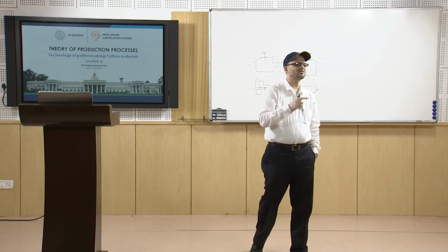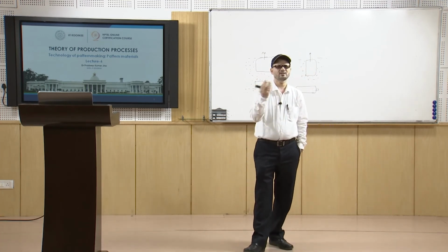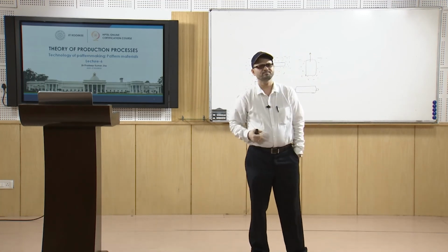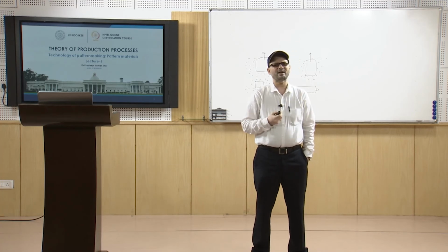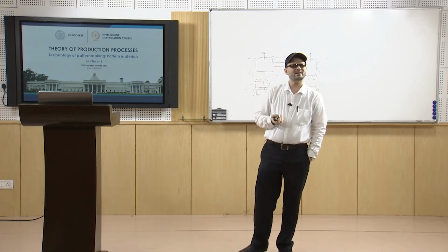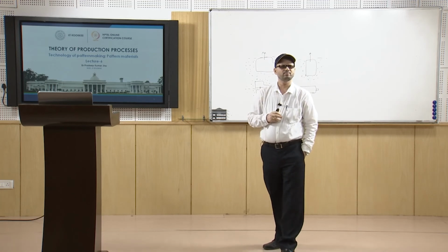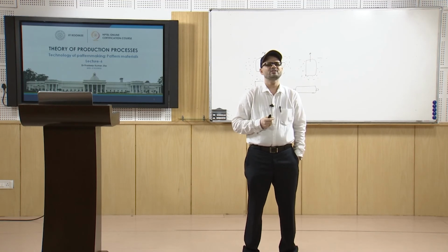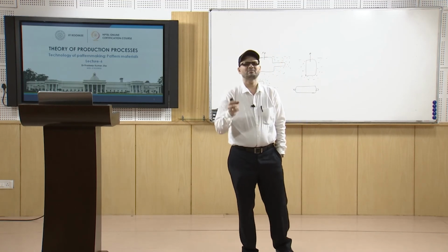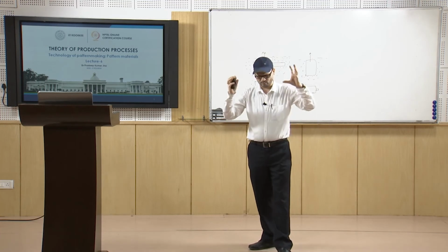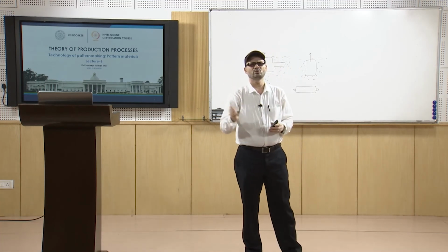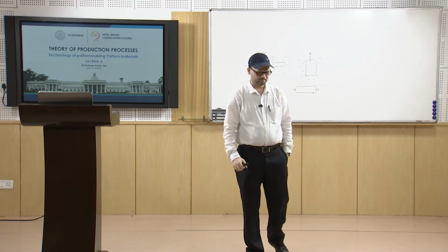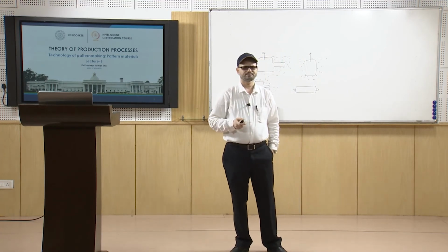So, that shrinkage of the casting can be offset. So, shrinkage allowance you can get it off, that allowance which you are giving, you need not worry about it. The gypsum plaster patterns can be prepared either by directly pouring the slurry of plaster and water into the desired shape, or by the sweep and trickle method. So, there are methods like you can pour it, or by the sweep and trickle method also you can have this preparation of this plaster of Paris pattern.